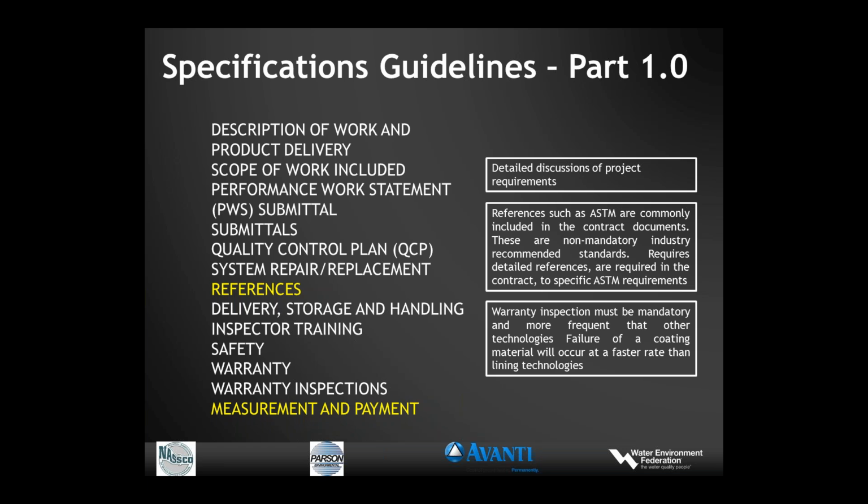And of course, your warranty inspections need to be mandatory and more frequent than for other technologies. I say that only because coatings and linings, when they're installed in a manhole, if they get defective, if they start having pinholes or pinholes remain, will start deteriorating fairly quickly.